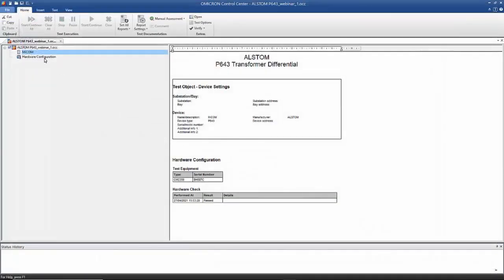Now we need to start with the hardware configuration. Let me now open the webcam or the camera to show you how we connected this protection relay with the CMC, and I will power it up. As you see here, now I will turn on the CMC. I already connected 6 current outputs, 3 combined generator cables, and 3 normal leads connected to the protective relay, which is already under test, and this is all through the test switches.